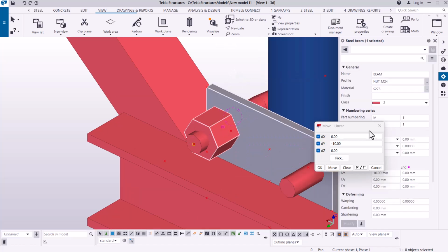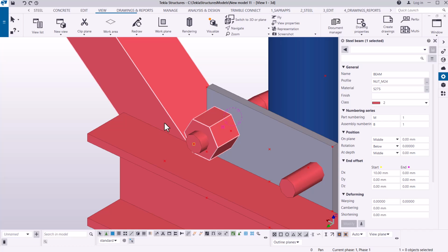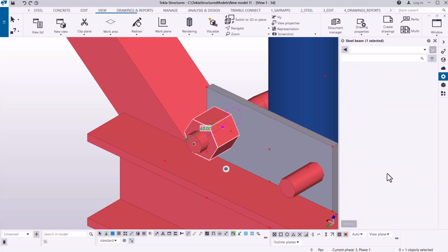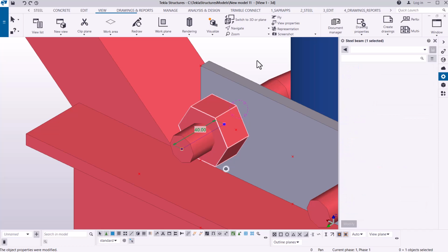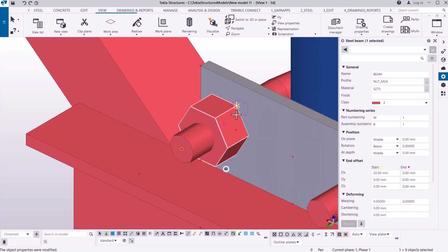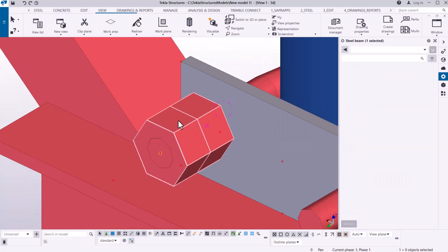And we can further reduce the thickness of our bolt by probably 10 millimeter. I'll select on it once again and come here and maybe give it 20. So under 20 there, I'll be able to select that and pick on that. So we have that in place.